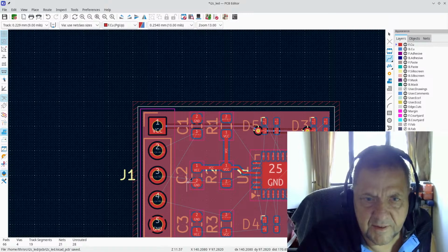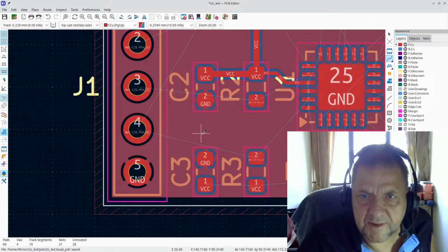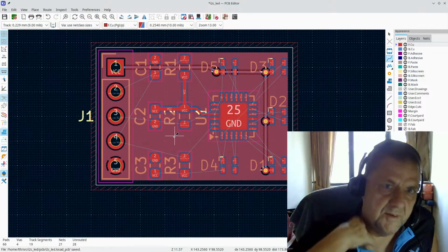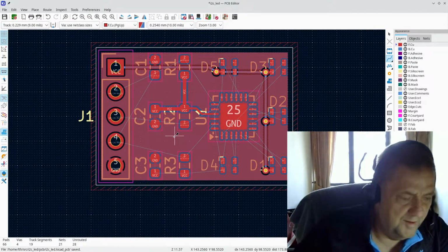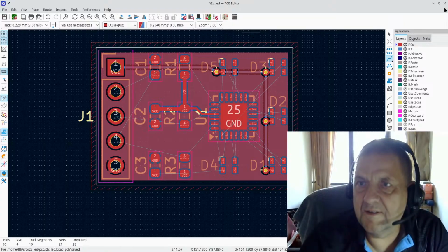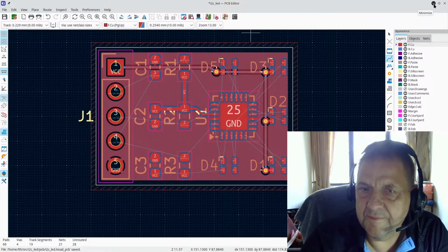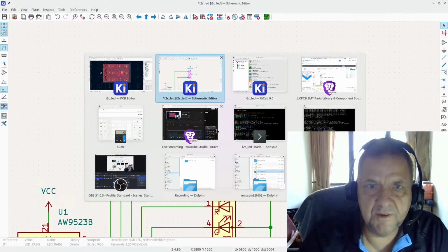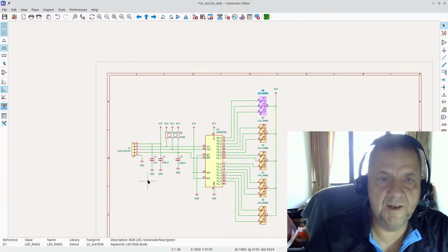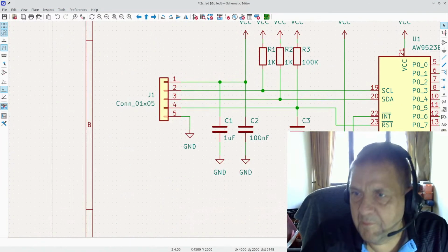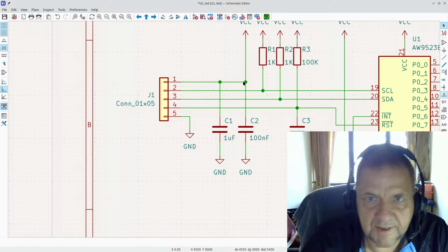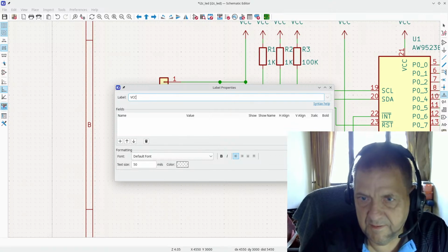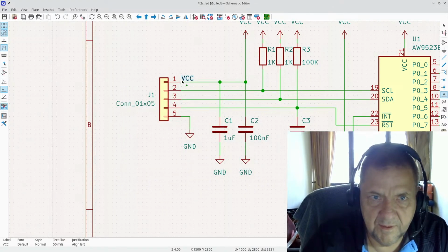I think we need to switch these two capacitors. I think that was the reset thing. So I've been lazy. Let me do this straight away, because this is getting a bit hard to follow. So let's go into the schematics, and actually let's put some labels on some of these nets. So this net is VCC. No doubt about that.